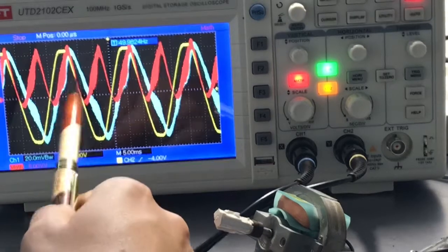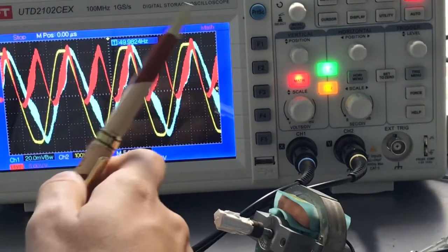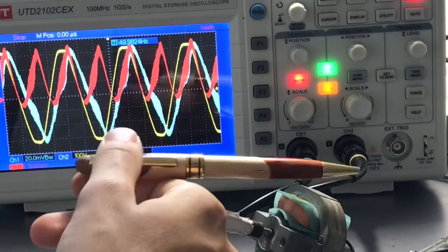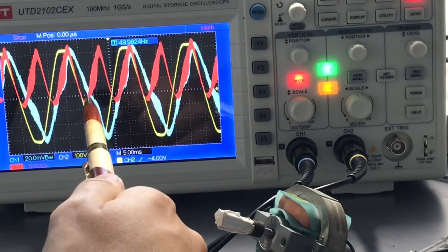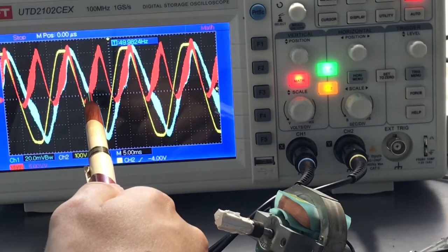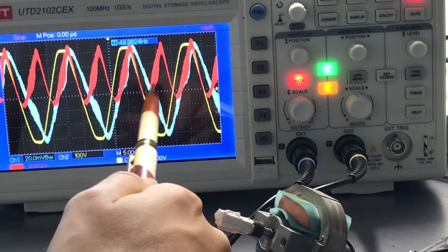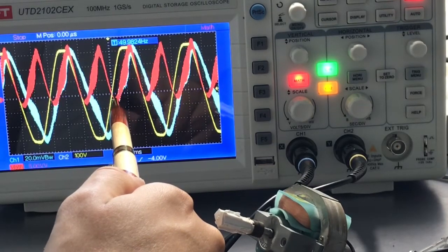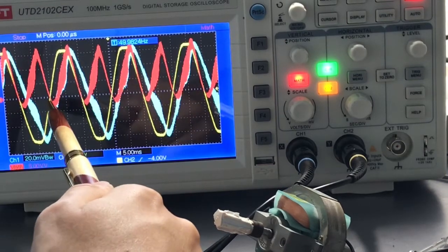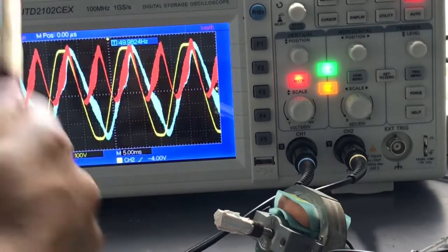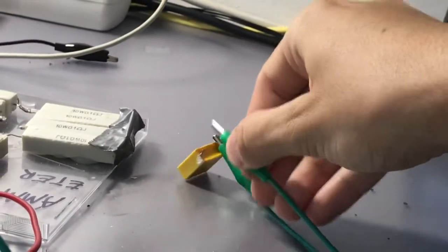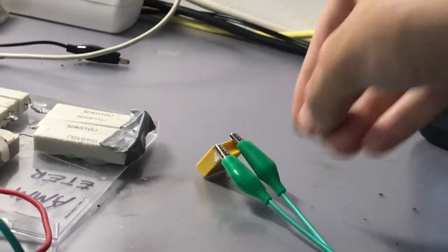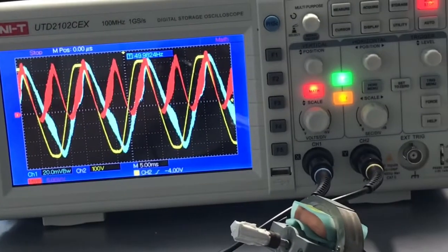And then what we see here is the power. Of course, it's not a true sine wave because the current drawn by the saturated core probably is nonlinear. But what we see here is basically the power is positive, but some of it is returned here, and those small little spots returned to the source, and this is what we don't want to see. So right now what I will do is I will connect this capacitor before running the circuit like that, and you will see the difference.